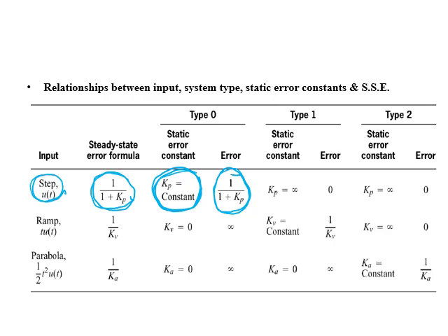At the same time, if I calculate Kp for one integrator or more, it is equal to infinity, which will give me zero error, because we will have more than one integrator. I mean, one integrator or more, that means the error will be 0. Similarly for type 2. Type 2 means we have two integrators. If two integrators, that means Kp is infinity and the error equals 0. You can think the same way on the other cases.